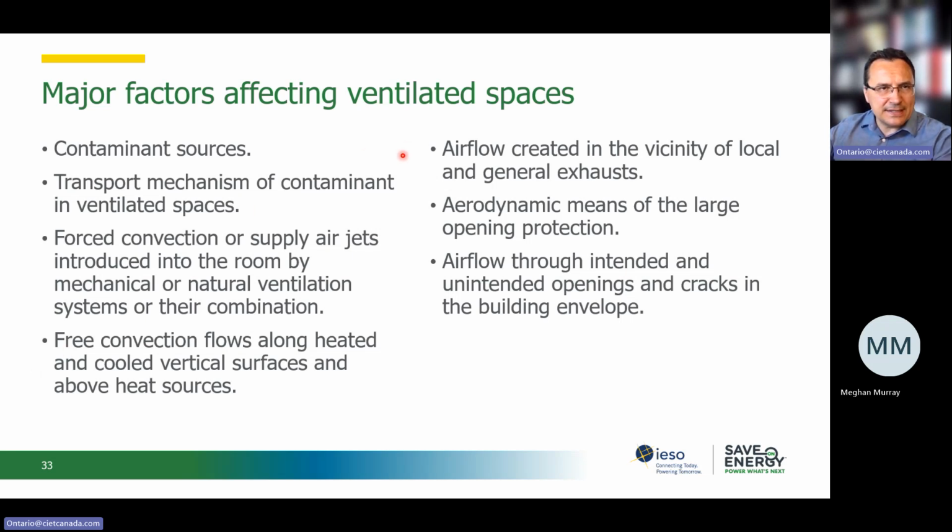We typically design, or we try to design, airflow near the source of the pollution. We will have general exhaust for the rest of the space. We rely on air transfer properties, the aerodynamic means for larger opening protection. Airflow through the openings and cracks of the building is accounted for. We have this secondary effect of fresh air coming into the building through these openings and cracks in the building envelope.